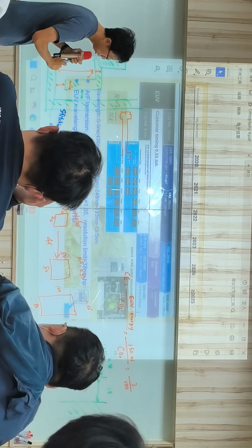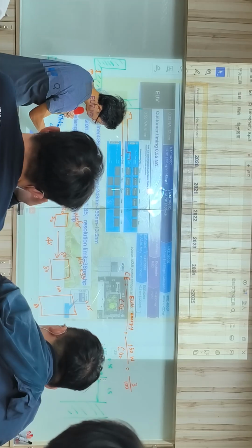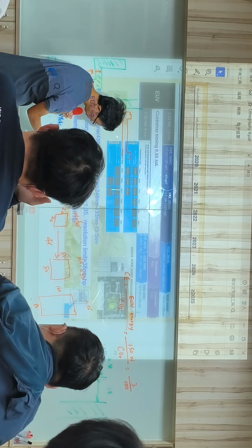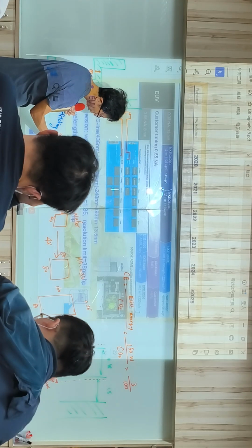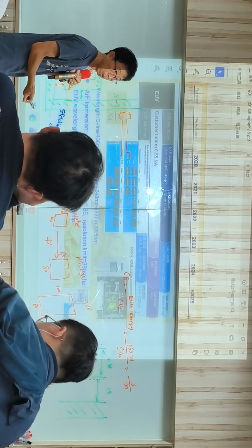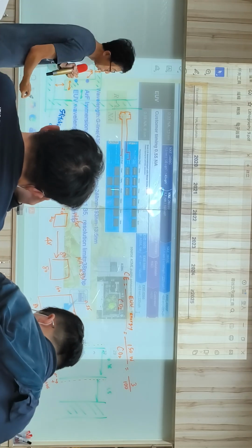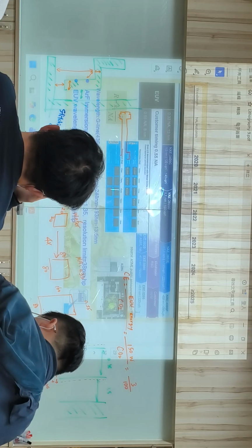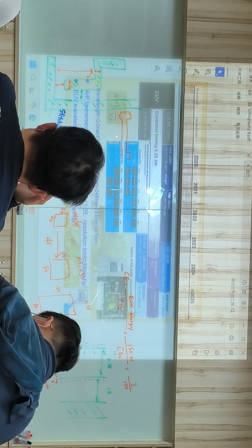So that means if you have a line here, your first exposure will only expose this part. Then your second exposure will do this part. So very likely your exposure may look like this. You will have some stitching problem.